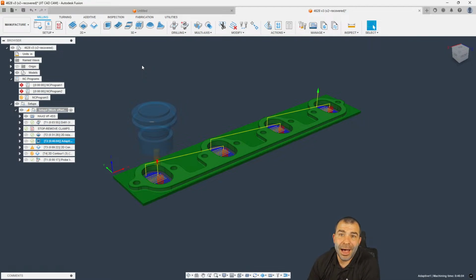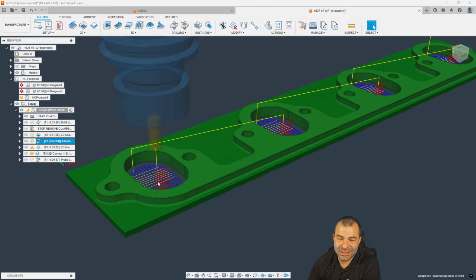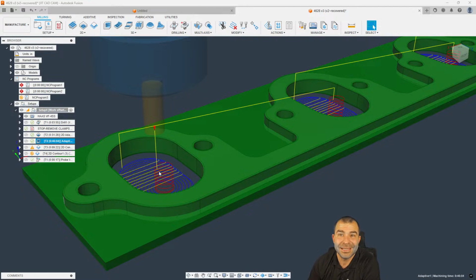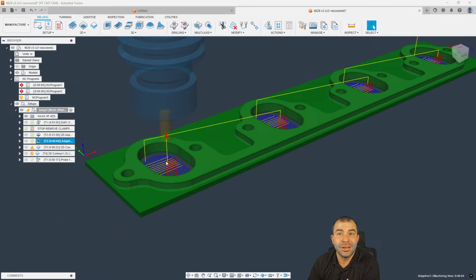Multi-core, right? So I am running, I think, 18 or 20 cores on my computer. And a lot of times when I calculate these toolpaths, I'm only running on 1 or 2 cores. The reason is that your tool moves in a single line or a single lane, so it really doesn't need a lot of cores. What it needs is fast cores.